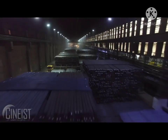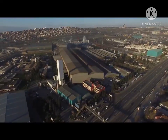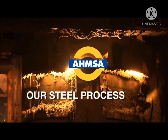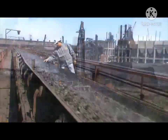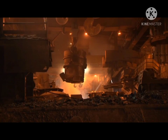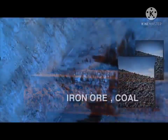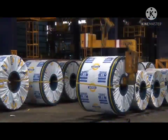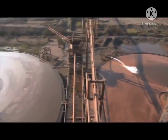To purify the steel, the furnace then blasts in oxygen, and lime and fluorspar are added. These substances combine with the steel's impurities, turning into slag. The slag then flows to the top of the molten steel where it is removed, leaving behind the pure steel. The EAF method is the most common steel production method today.